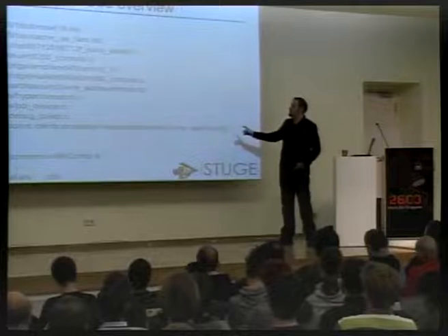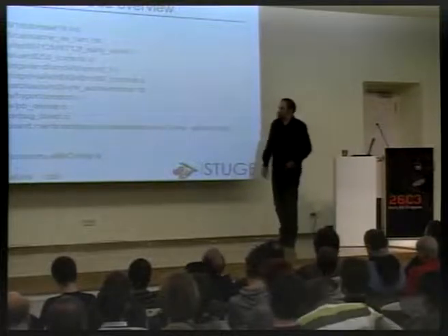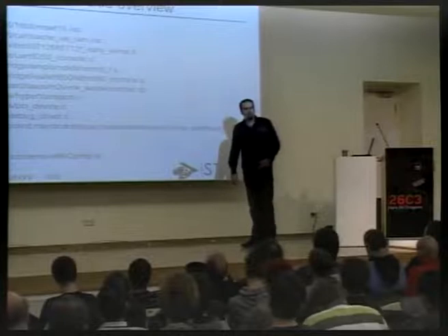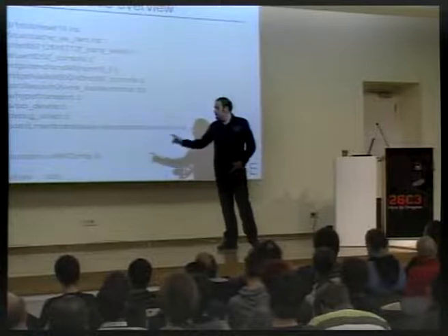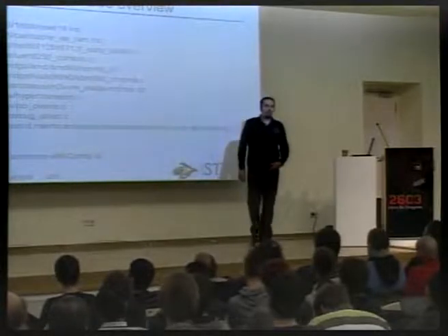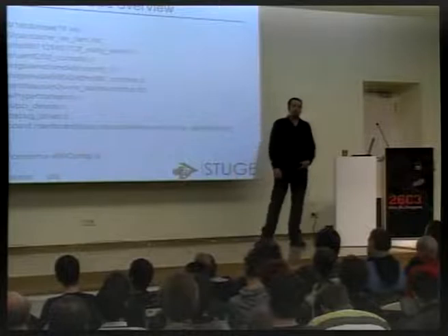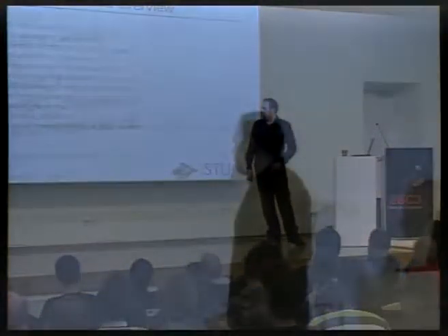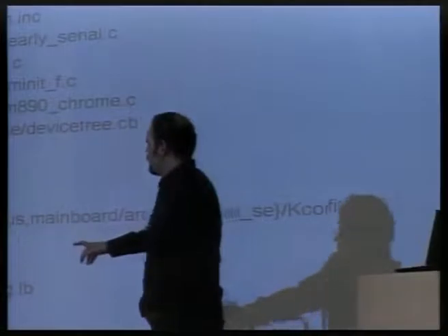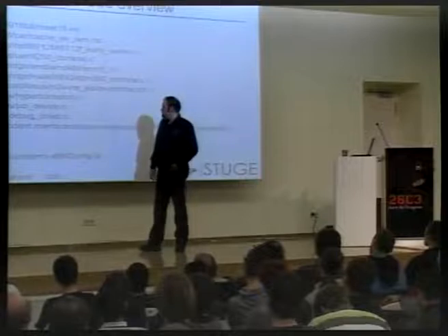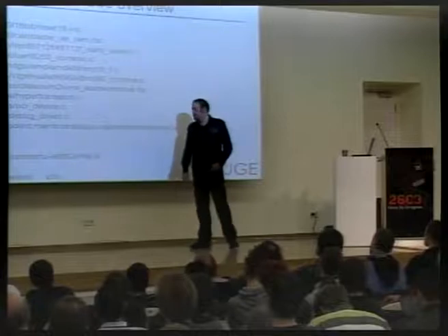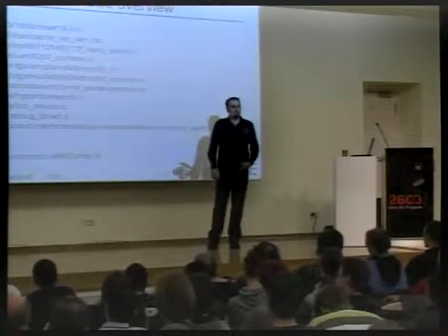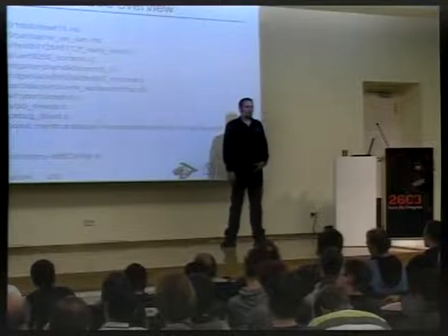The kconfig files are used with the kconfig system, but kconfig was introduced fairly recently in the current codebase. And before that, we used the targets subdirectory quite a lot, and for some mainboards, it's still necessary to use that. There you create, first of all, a subdirectory for the vendor, in this case emulation, because it's an emulated vendor, I guess, and then you create the board name subdirectory, in this case QEMU, and finally you put a config.lb file there, which you